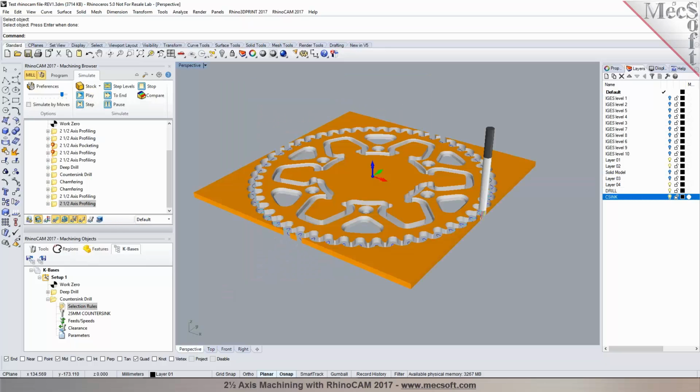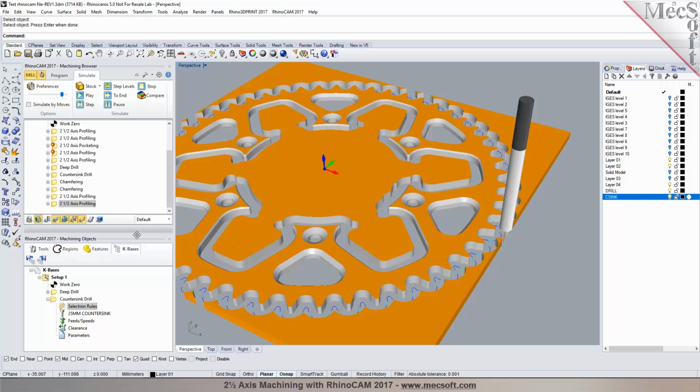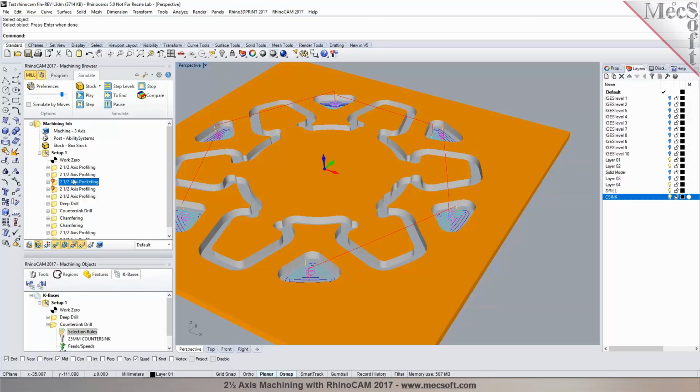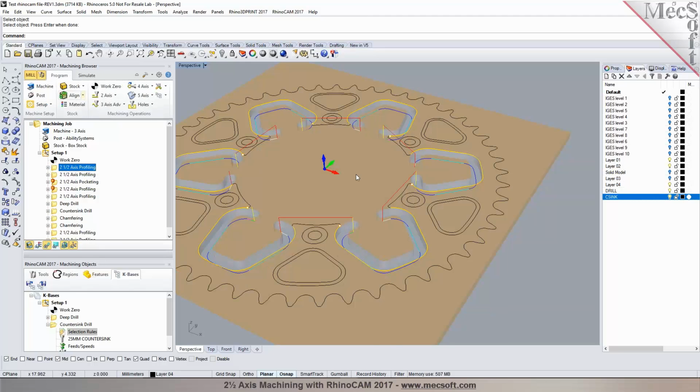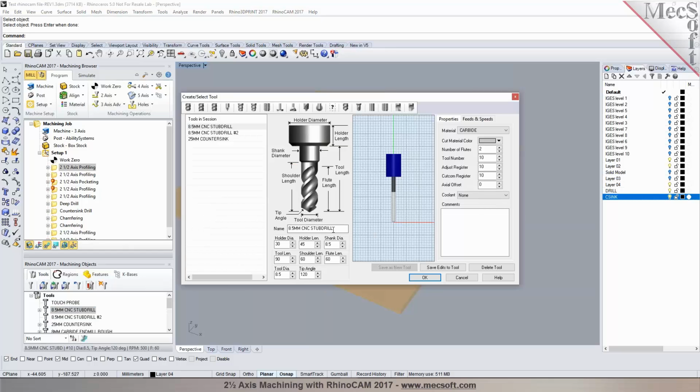Okay. The only thing is that I like to add a lot of comments to my programs. Between each, obviously it's going to select a few tools there, so giving the tools names, descriptions of the tool. Now those things can be automatically handled in the post processor, so there's a couple of things you could do to improve it as well. As we can automatically output the tool name as comments. We can also type in any comments in addition to the tool information that you already have in here to be output in here. You can put that in there and we can output that as well.